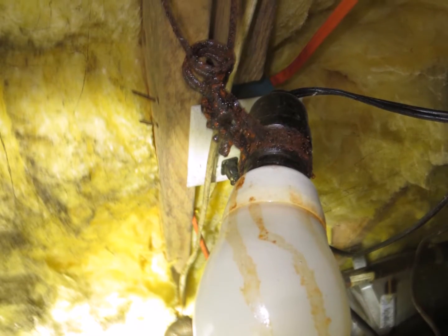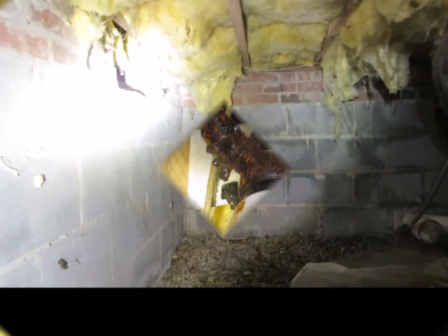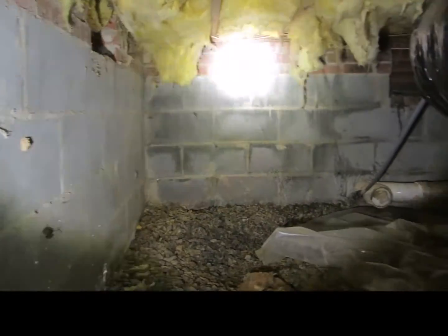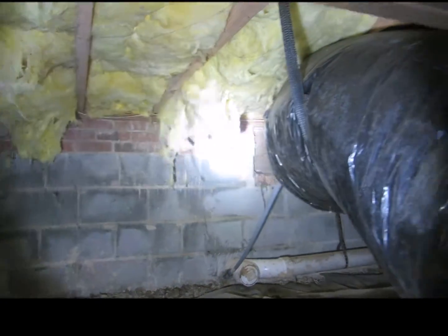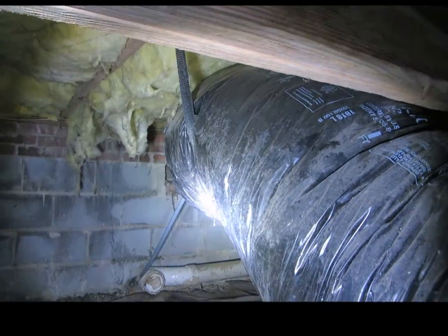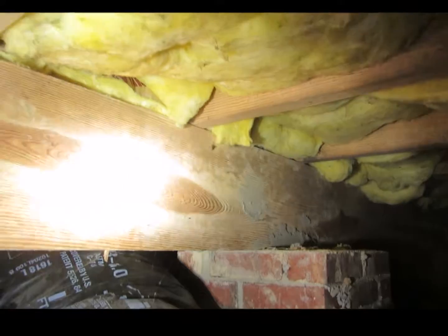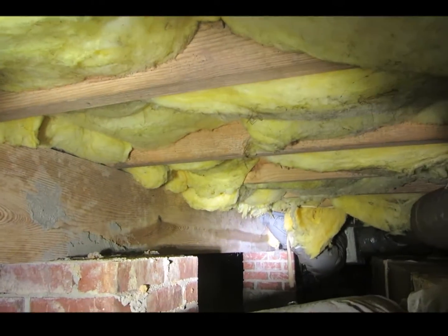Another shot of mold on the main beam. Extensive mold growth above the air handler. We have an open foundation vent crawl space that's having humidity issues, so it's getting the insulation wet and pulling it down. The air ducts condensate seasonally, so they have extensive mold growth on them, and the main beam also has mold growth established on it, as well as to a lesser degree the actual joists.